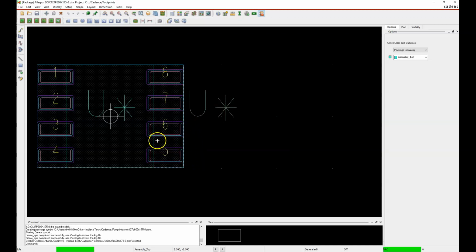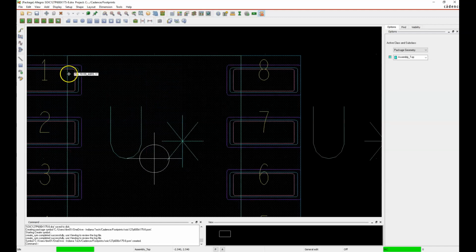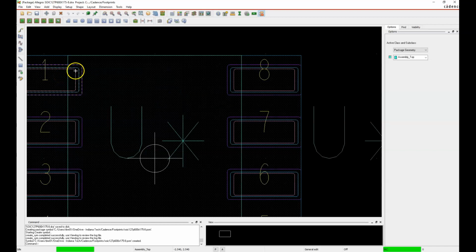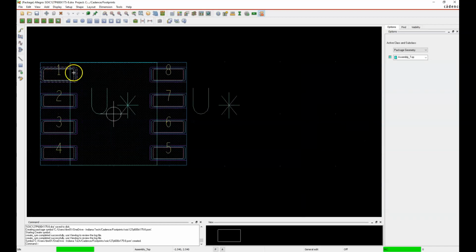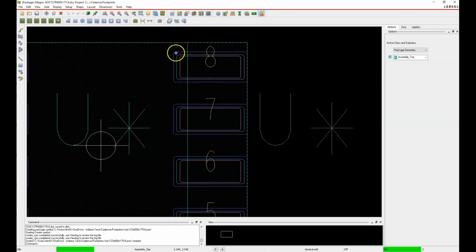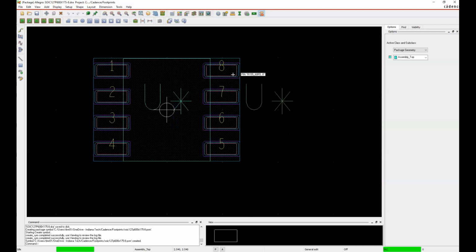And then you can see here we've got our nice little landing pads, and we've got the package width here. You can see that there's a tiny bit of overlap of the copper underneath the pin there, but that is a fairly typical thing for us. And then you can see the different layers, the solder mask layer and the solder paste layer. And then we have our footprint.